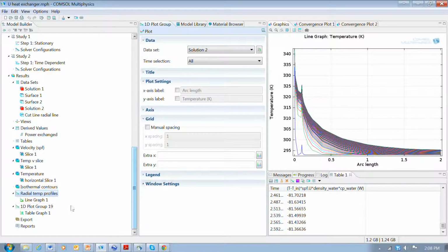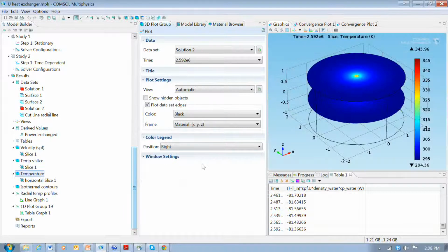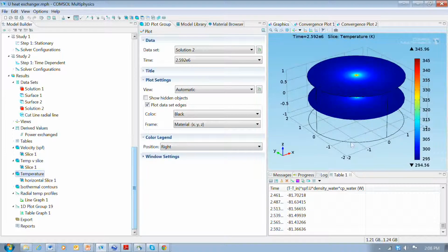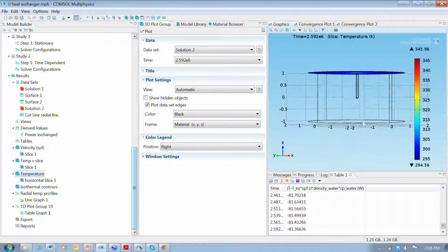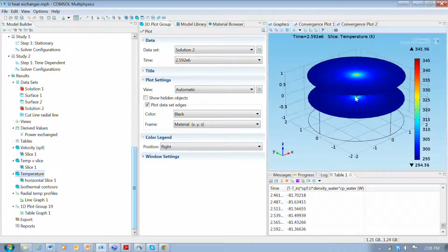The other thing that is worth noting here is that the cylinder has no flow and it's insulated on the top and the bottom. Now, this is probably okay at the bottom, although we might want to make it a little bit deeper. But at the top, we would have the ground surface at some point. So what we're assuming is that this is really quite deep, so we're not interacting with the ground surface, and we're not having an effect there.